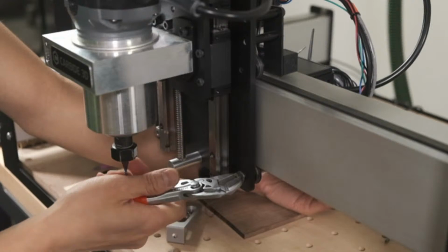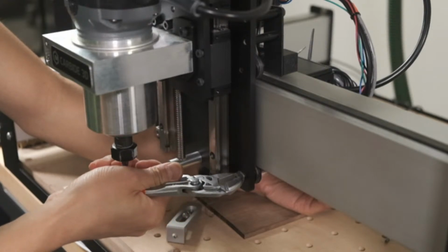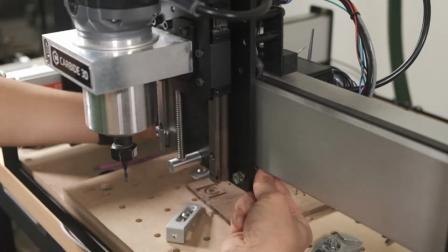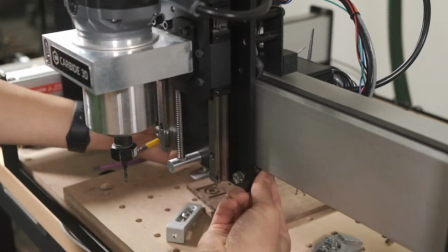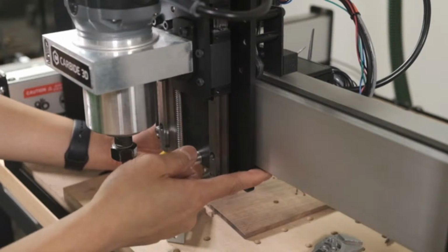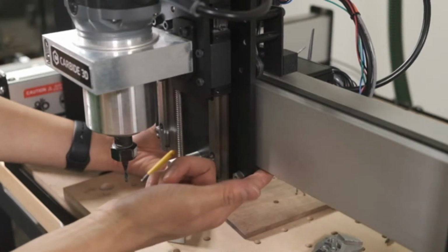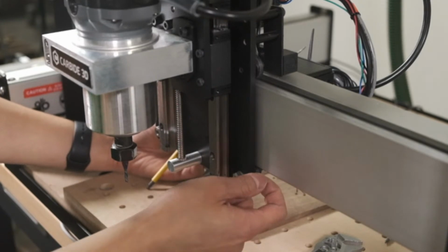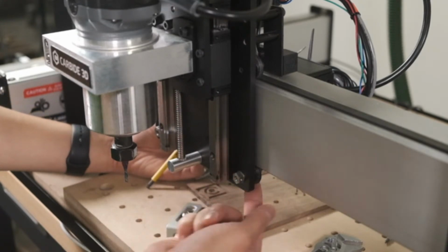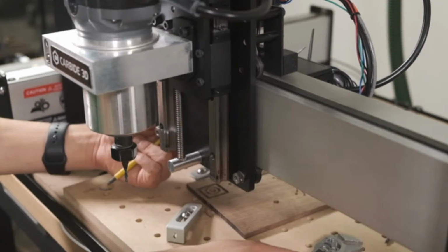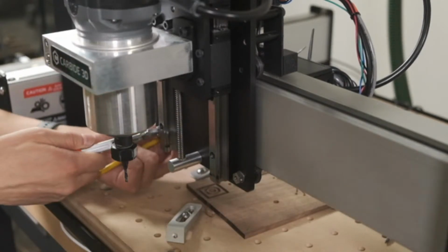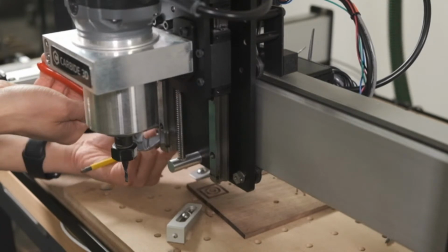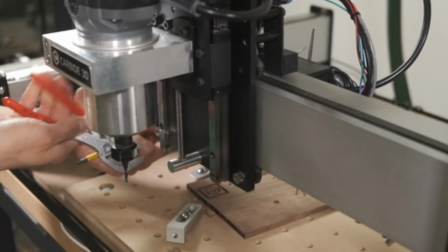So another, not even a 16th of a turn. All right, I can just barely spin that wheel. Before you do this, you should also wipe down your rails, make sure they're clean, take a little toothbrush, make sure there's no built-up dust on your V-wheels. And then this one is good. I'm going to quickly do the other one. Close enough, that's good.